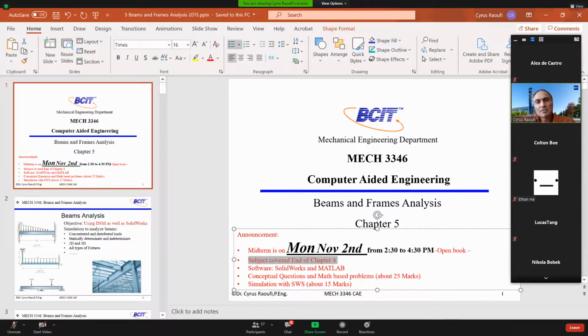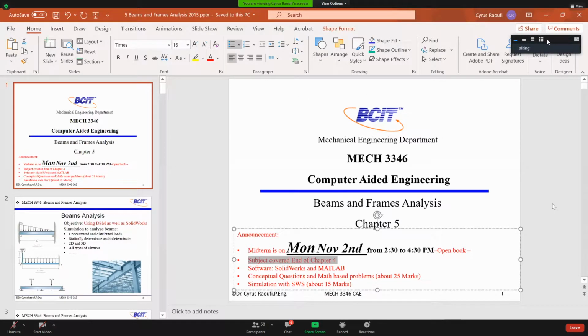In chapter 4, we started with the one-dimensional beam element, and we said there are 2 approaches. If you remember, one approach is to use traditional solid modeling techniques and create extrude, revolve, and so on. But if you have more than one segment, you need to create a multi-body environment, meaning that when you apply revolve or extrude, make sure that you uncheck merge result. And then when you are moving to the SolidWorks simulation environment, you are going to just treat the solid as a beam element.